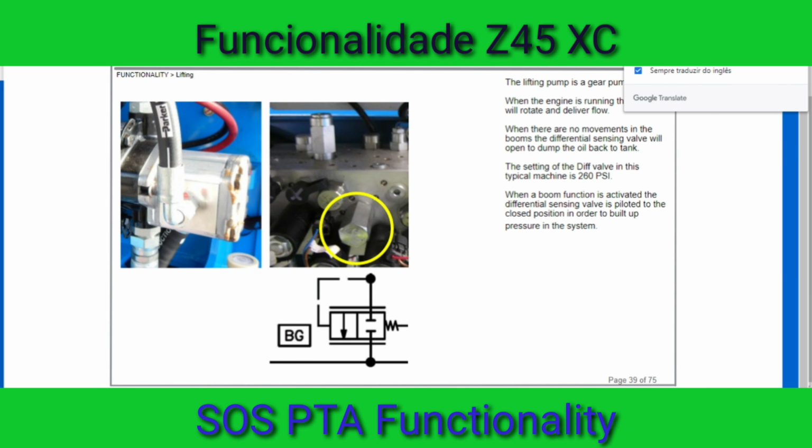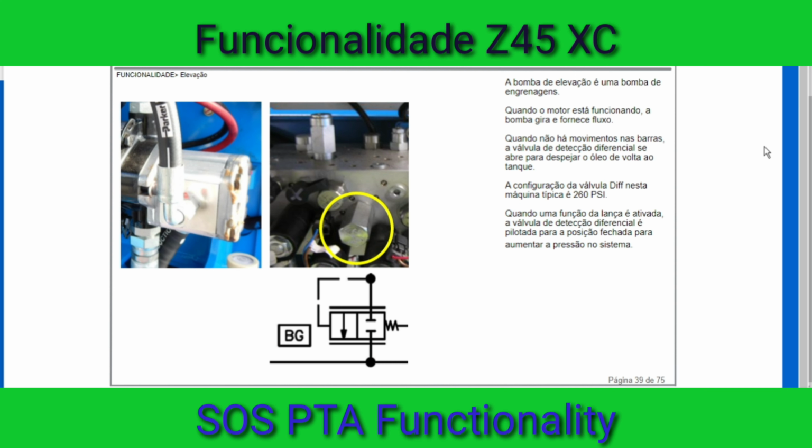The lifting pump is a gear pump. When the engine is running, the pump will rotate and deliver flow. When there are no movements in the boom, the differential sensing valve will open to dump the oil back to tank. The setting of the diff valve is in this typical machine 260 psi. When a boom function is activated, the differential sensing valve is piloted to the closed position in order to build up pressure in the system.